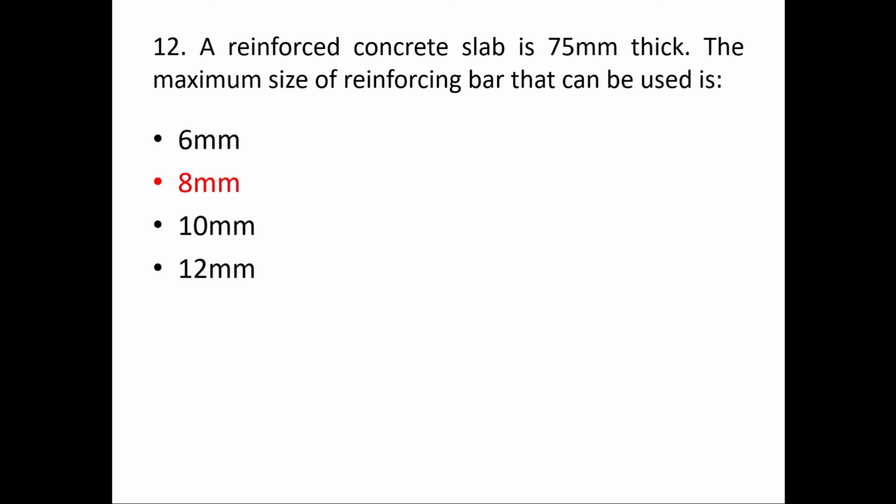So for a maximum size of reinforcing bar, we are having a thickness of 75. So 1/8 of 75 is 75 by 8, which is about 9. So the maximum size of reinforcing bar is 8 mm in this case. Okay, so you have to keep in mind the clause of Indian Standard 456/2000. So move on to the next question.